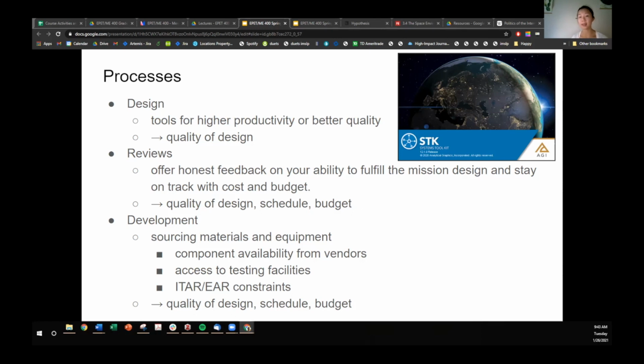For example, we'll be getting a Systems Toolkit tutorial from Dr. Miguel Nunes today, where we can plot an orbit, show the ground track of a satellite, which is important for Earth observing satellites and for ground station tracking. And we can extract the intensity of the sun during an orbital profile, which is important for power generation purposes. We used to have human computers, people who would calculate orbits and approximate the amount of power that a satellite can generate over an orbit. But now we have STK, which is a more precise software application that streamlines this whole process.